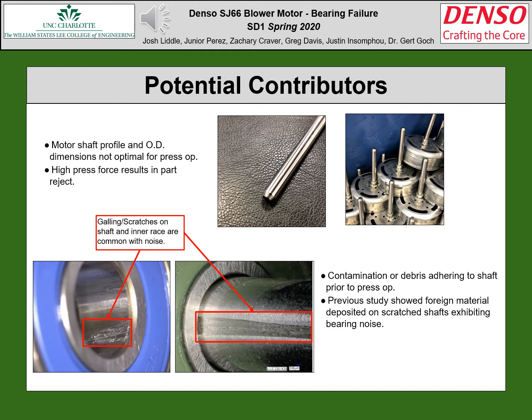External factors such as debris from the rotor balancing stage and other machining operations were also noted as being contributors to scratched shafts, which are commonly found on motors with excessive levels of bearing noise.